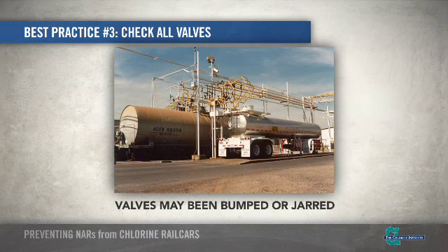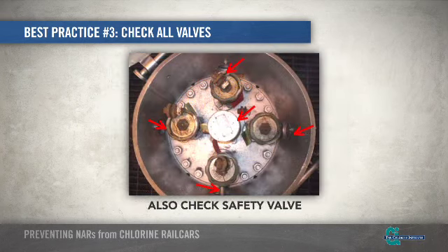A possible cause of these leaks is that the unused valves could have been bumped or jarred slightly open in transit or during the unloading process. Don't forget to check the safety valve as well.